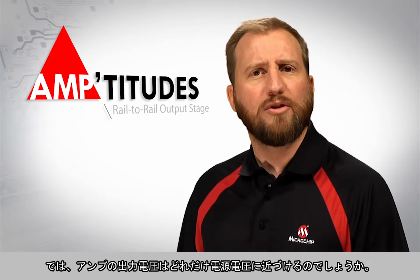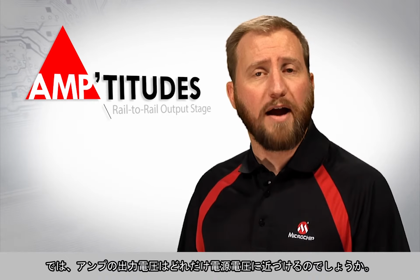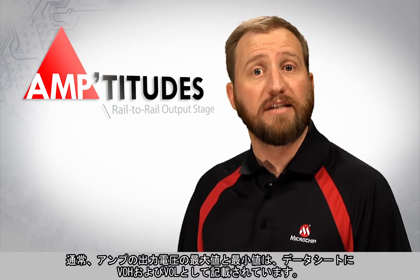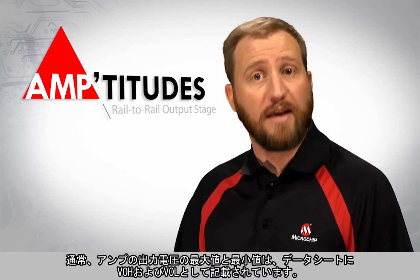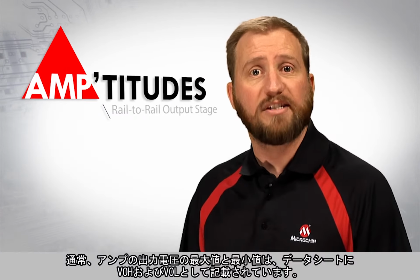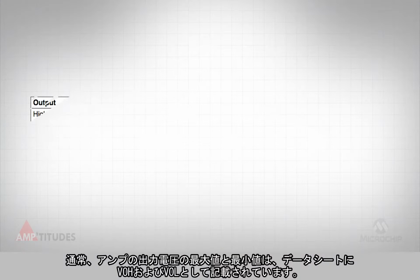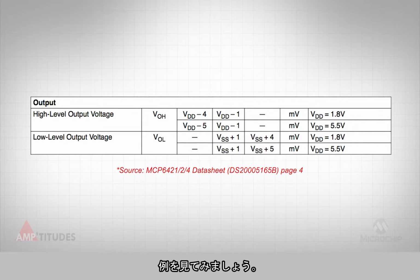So how close to the supply rails can a given amplifier output swing? Well, this specification can be found in the amplifier datasheet and is typically noted as VOH and VOL, which stands for the high level and the low level output voltage respectively. Let's take a look at an example.